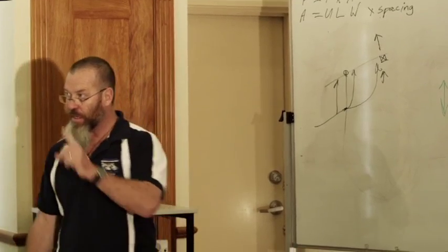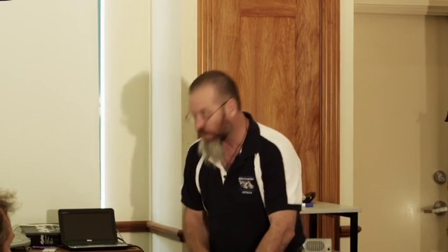All right, now you think about your M12 ChemSet bolts. I was saying to Damien, a guy gave me one, it was about that long. You use them? 200. So it's got to be 110 mil into the concrete, and then you've got the rest to tie your plates down. If they were, no, there wouldn't be double plates, it'd be single plates. Anyway, that's what they give you. Your minimum edge distance is 50 mil. So ChemSets work. They actually work, and they will give you, in 20 MPa concrete, 10.8 kilonewtons of resistance. So they'll give you more resistance anyway.